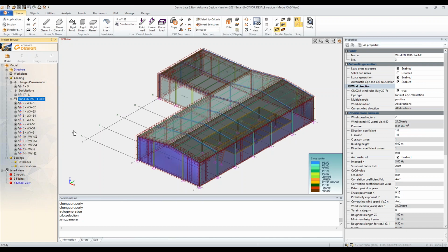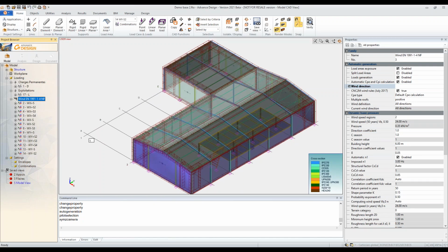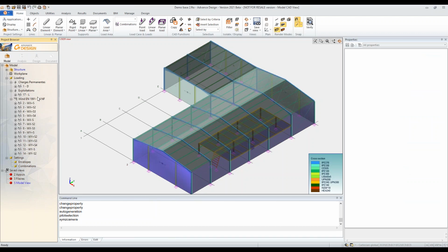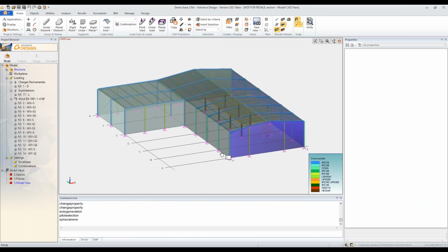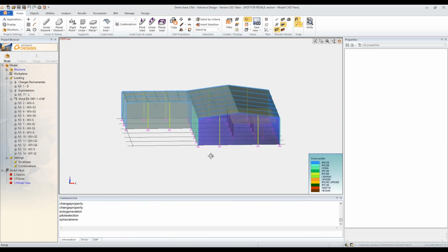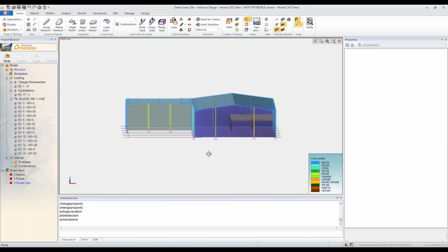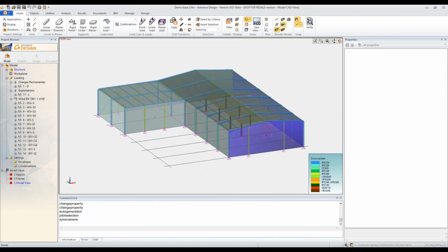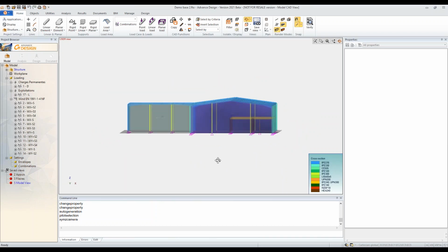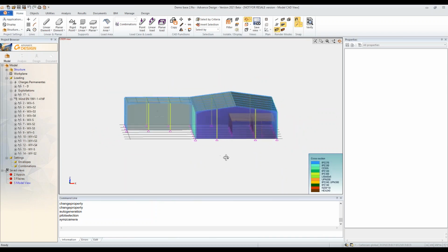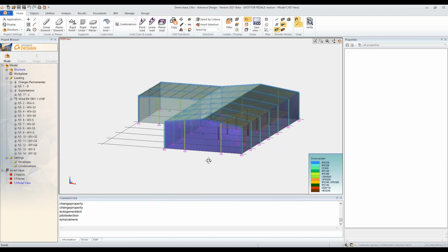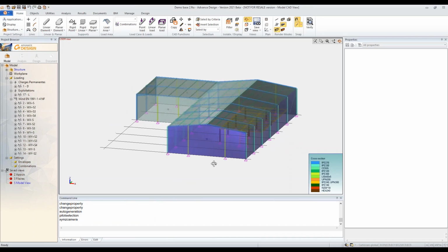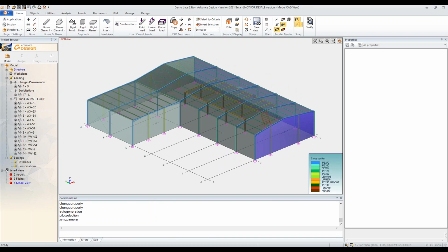And we've got quite a lot, because the Eurocode 1 tells us to have that many, especially when you're dealing with such a building shape. When you have horizontal discrepancies, considering a pure X wind or pure Y wind is not enough because of the setback here. Actually, for each main direction, you have to consider a 45 degrees in and a 45 degrees out. So it doubles the load cases, because the wind effects will be completely different.